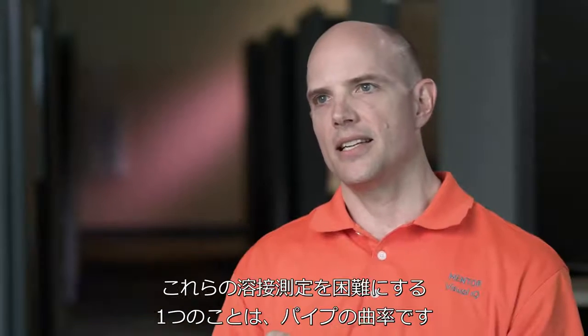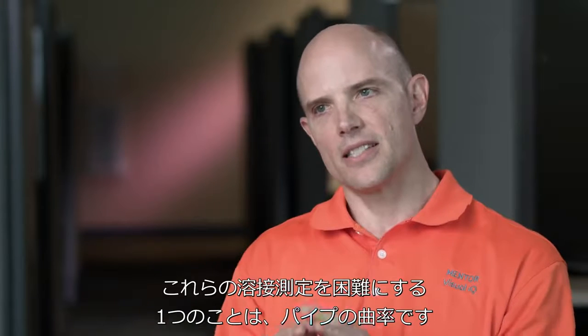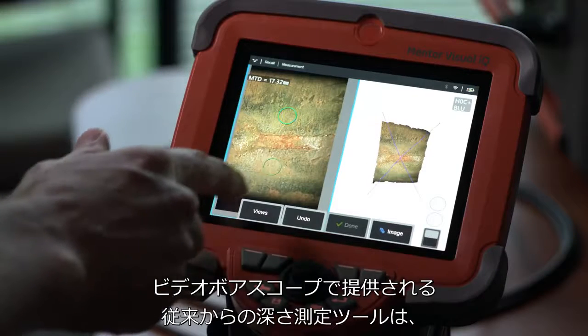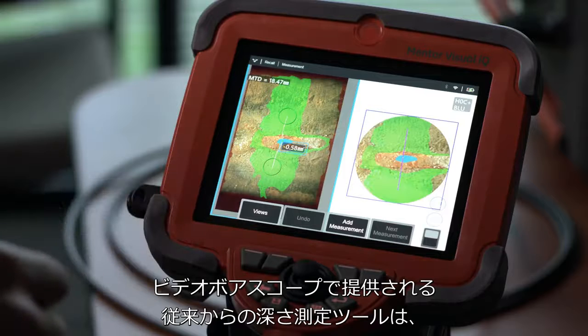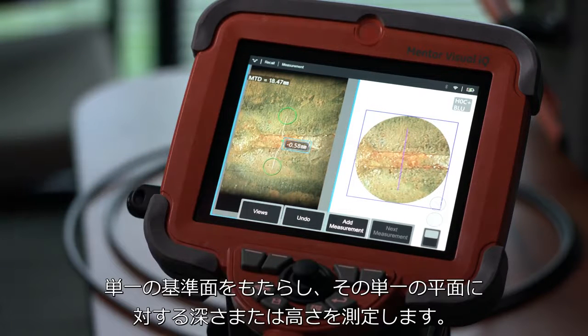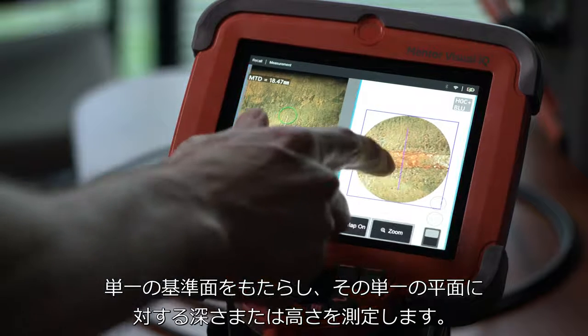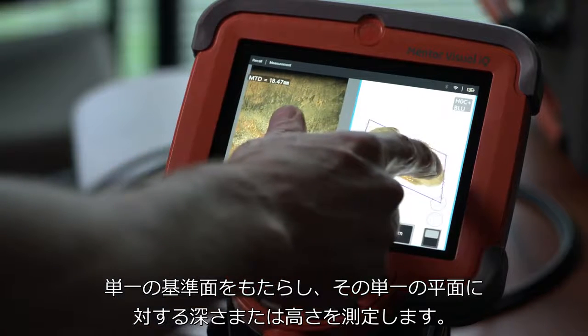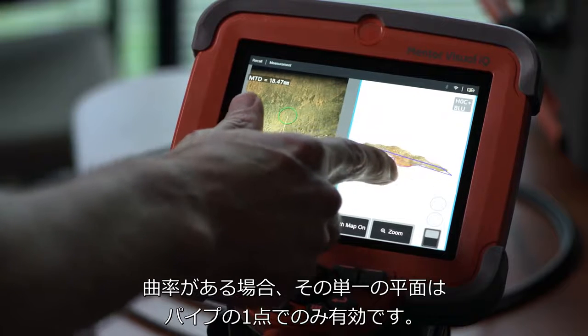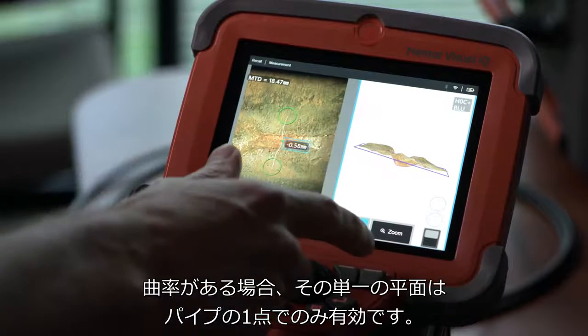One thing that makes these weld measurements difficult is the curvature of the pipe. So the more traditional depth measurement tools that are offered on video borescopes work on a single reference plane and measure the depth or height relative to that single plane. If you have curvature, that single plane is only valid at one point in the pipe.